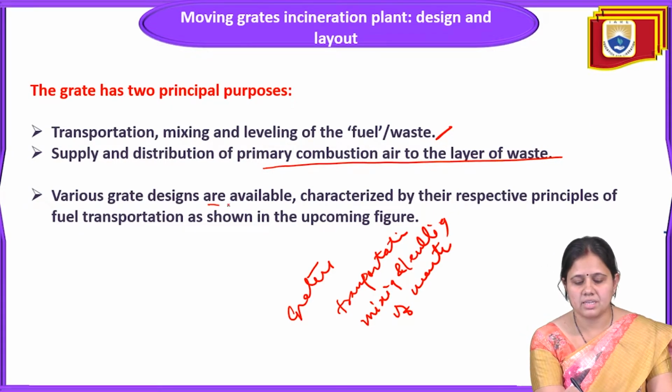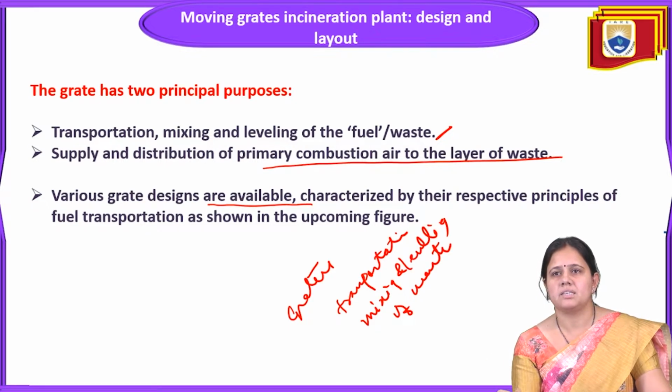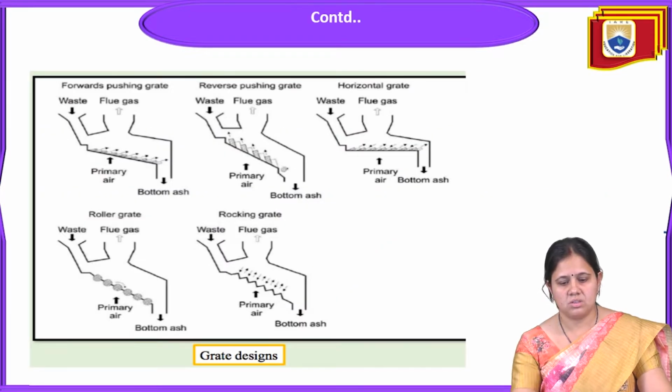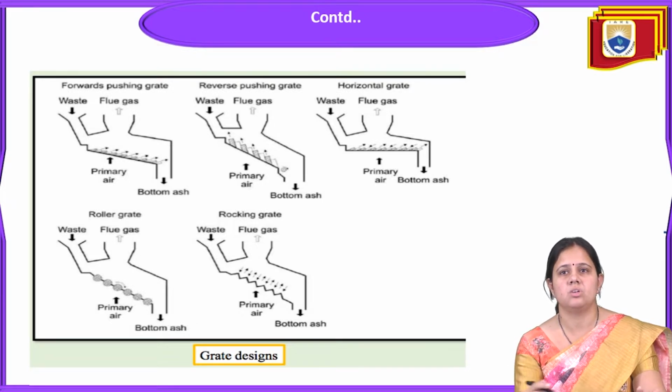Various grate designs are available. Many designs are there, and these designs are characterized by their respective principle of fuel transportation, which I will show you in the next picture. So this is the picture related to the grate designs. First of all, you can see this one is a roller grate.